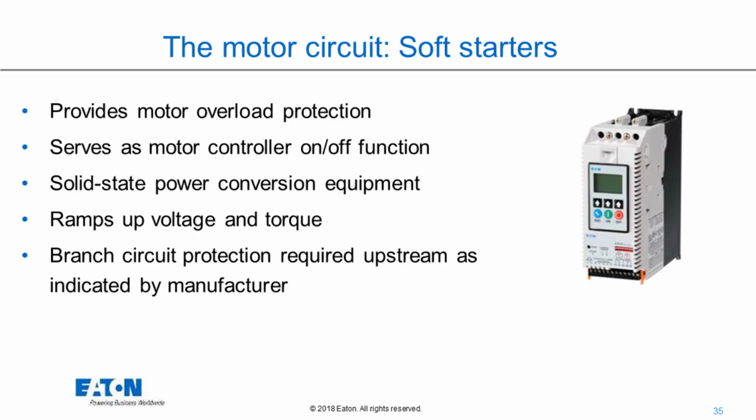There's a soft start starter. It provides motor overload protection and serves as a motor controller on-off function. It's another piece of solid state power conversion equipment. It ramps up voltage and torque. It's to avoid an across the line full voltage start, which a lot of industries try to avoid.